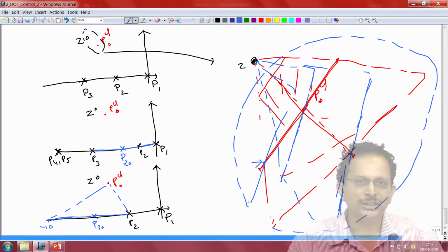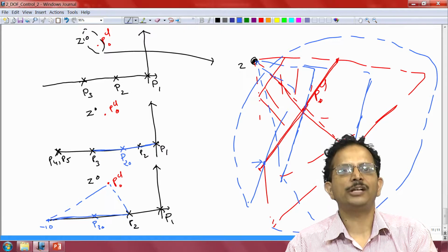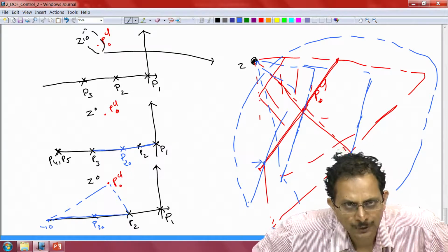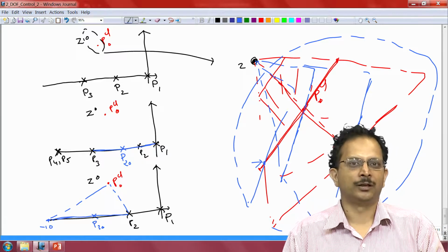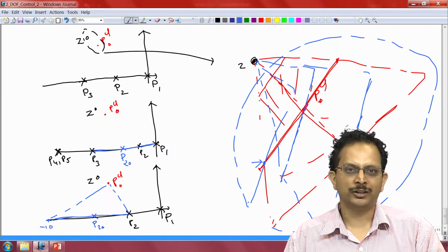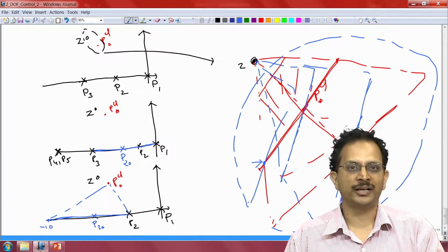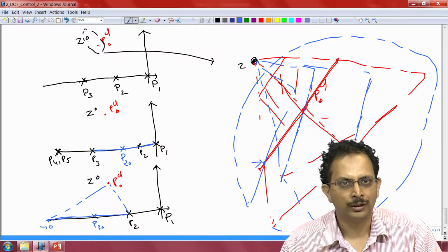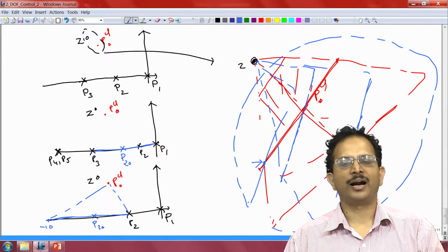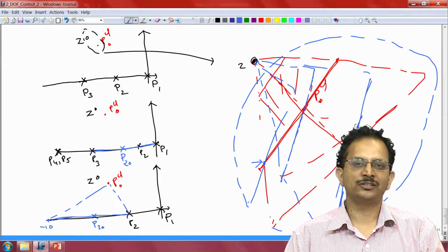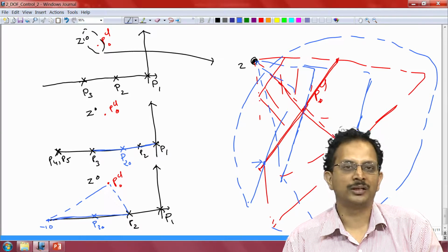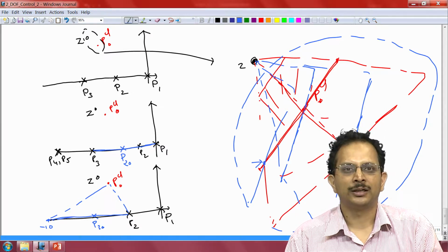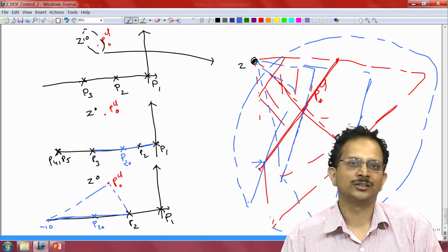But with that additional step taken into account, one can in a very straightforward manner undertake the rest of the design, determine the numerical value of x, and subsequently undertake the remaining steps in the design where we determine the angle of the point z with respect to the point PCL naught and hence use it to determine the exact position of z, and then determine the location of the far away poles P4 and P5, and then the gain of the feedback controller, and as a last step the structure of the pre-filter. Since these steps are identical to the ones that we undertook in the first clip where we did 2 degree of freedom control design, I shall not discuss the details of these steps in this clip.